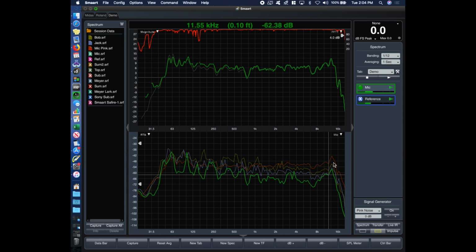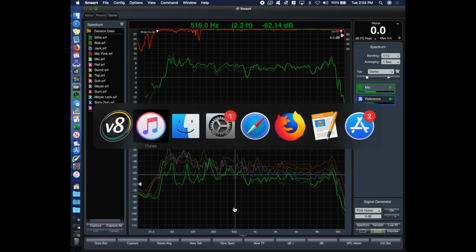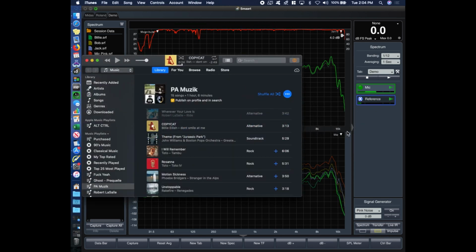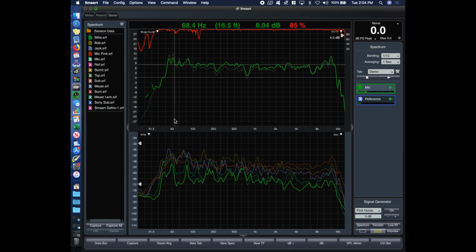So we've just gone through several different songs, and spectrally they all sound quite different, and we can see that manifest itself down here with the various RTA responses that we have. But other than just the changing in overall level, our FFTs remained constant. Does that all make sense? So when we talk about having a flat sounding PA, what we're really saying is that we have a transparent sounding PA. We don't really want something to sound flat necessarily. We just want it to sound consistent.